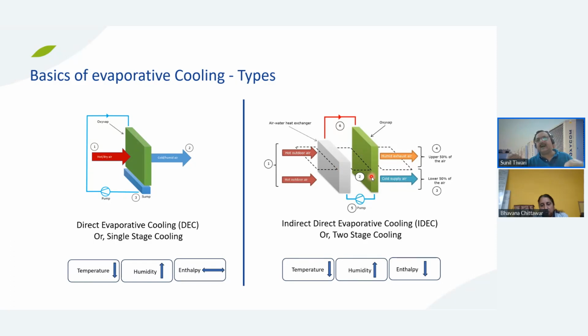So you look at normal direct evaporative cooling and air conditioning. So probably the two-stage evaporative cooling is a process that supplies air with a thermal quality which is between these two, superior to direct evaporative cooling. And in terms of thermal comfort, little inferior. It can't break the dew point and reach the dew point. So it will be a little less cool than the air coming from the air conditioner. So that's the positioning of two-stage evaporative cooling generally. But yes, with the right selection of application, right explanation, the masses are shifting to go for two-stage evaporative cooling method now.